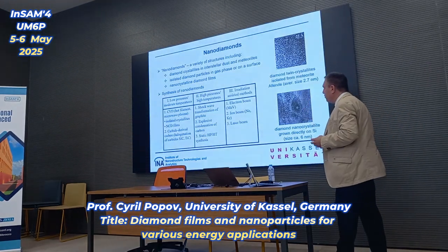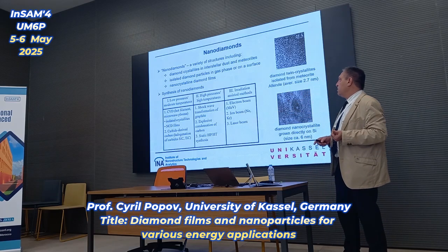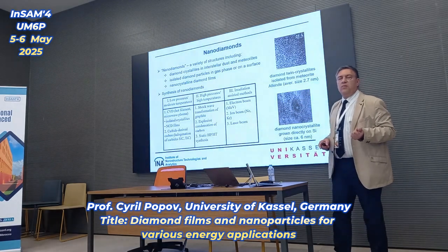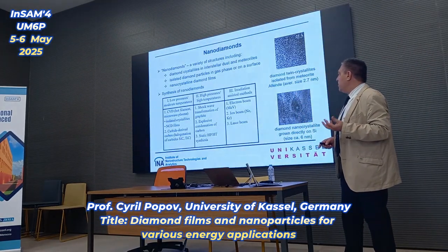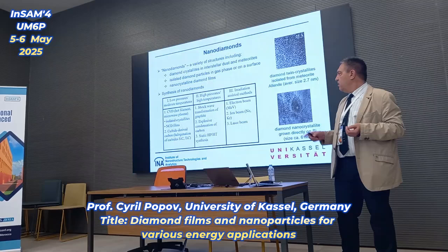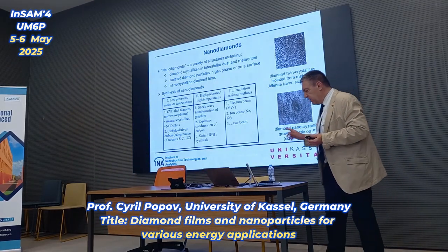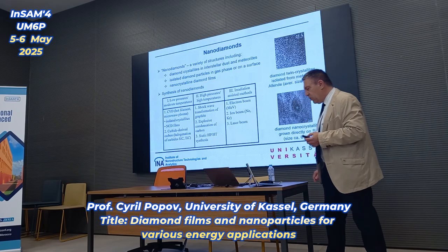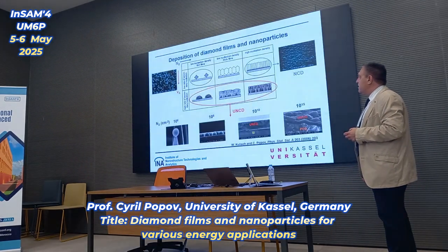And the third group of methods are the so-called irradiation-assisted methods, the application of electron beam with mega electron volt energy, so heavier ion beams like neon or krypton, or application of laser beam. So these are the techniques that can be used to prepare nanodiamonds.